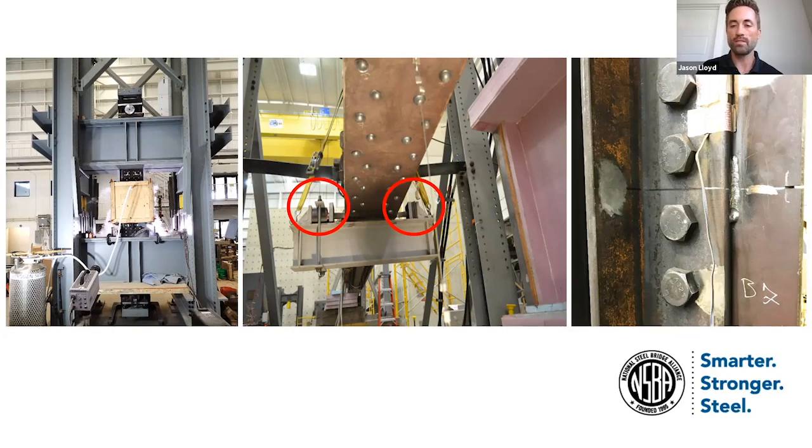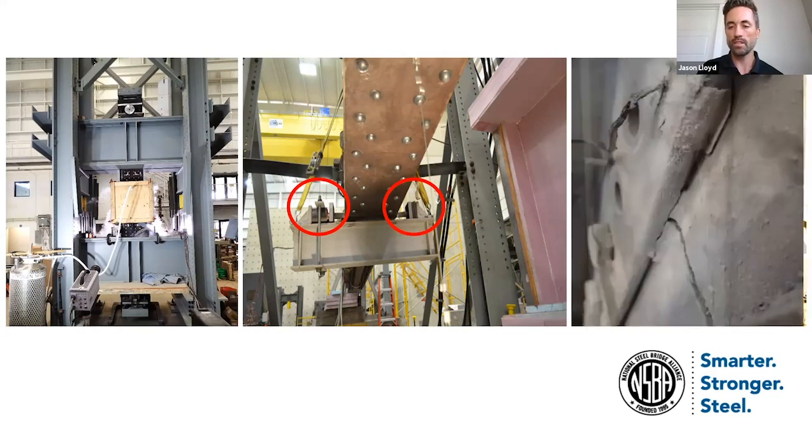However unlikely it would be for them to be in the path of fracture, we wanted to see if it would provide a path for fracture into an adjacent component. The good news is that the tack weld did not, and as you can see now on the image on the right. The fracture tests were extremely harsh tests, and we found that fracture could not propagate across component boundaries and sever an entire cross-section.